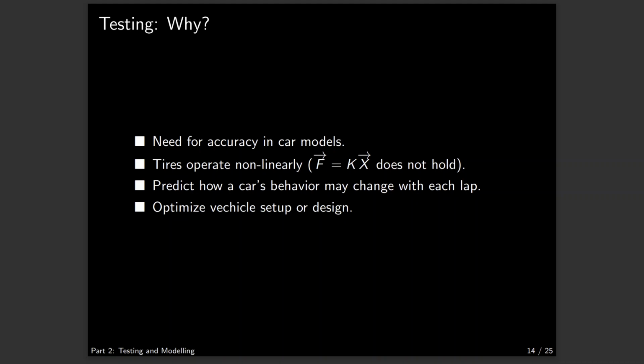So, why do we test? It's typically a good engineering practice to test our designs and ensure that they behave as we would expect them to given a certain type of stimulation. Moreover, proper testing yields us the necessary data to validate our decisions. In the case of tire testing, we use this information to begin developing our tire model, which is the most fundamental element of a car model.